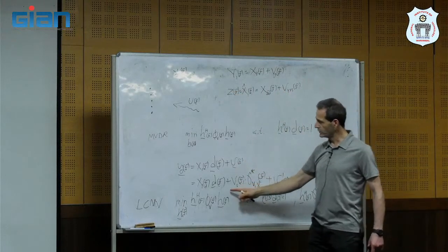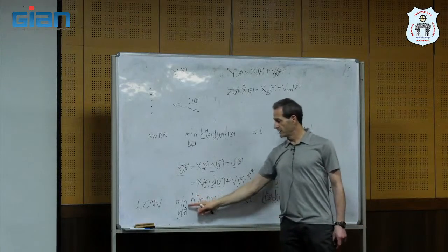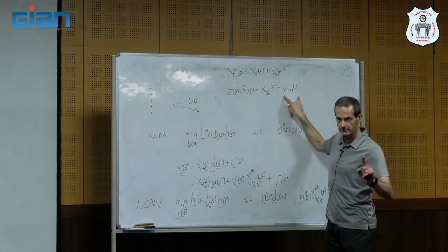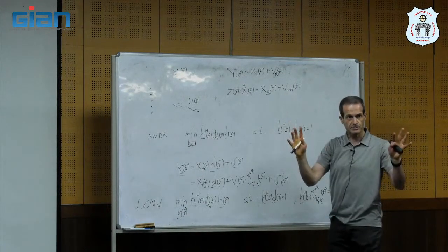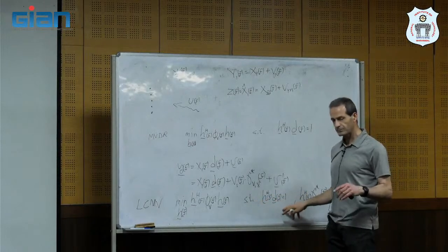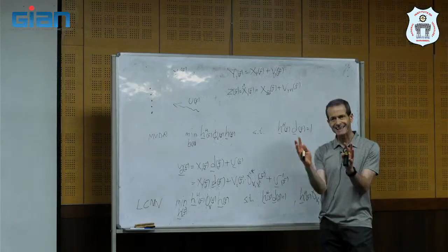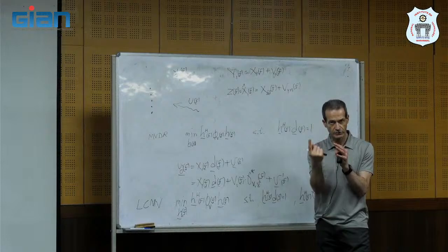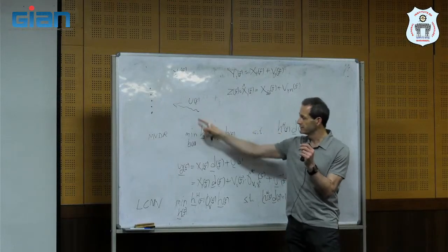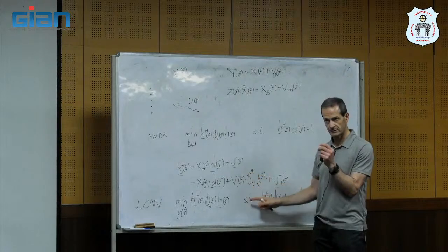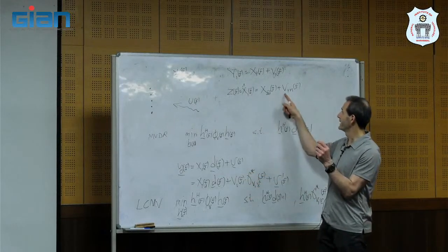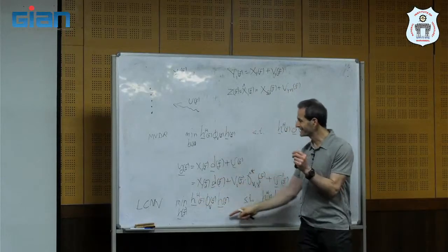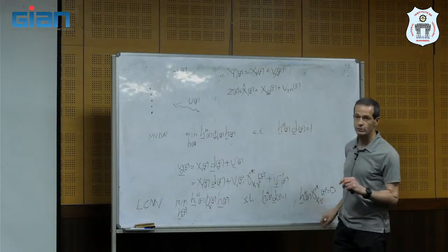And then we try to minimize the variance of the residual noise under this constraint. So the signal subspace, we don't touch it. You see, signal subspace, we don't touch it. But within the noise subspace, we add an additional constraint that the noise, the coherent noise, will be zero at the output, and we try to minimize its variance under that constraint.